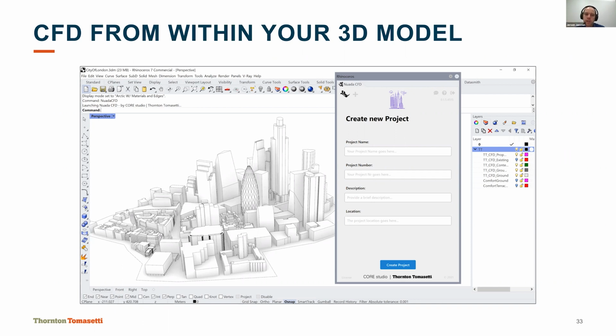What I like about SimScale is they have a specific solver for urban domains, that is Boltzmann solver, which, without going too much into detail, technically doesn't mesh the geometry, and therefore it's actually very gentle with geometry. So you can throw in quite a lot of dirty geometry, which means you save a lot of time in cleaning up the geometry. If you're working with an OpenFOAM big model like this, you could easily spend 2-3 days to actually remodel everything. And with SimScale, I've been seeing that drop to almost an hour. The simulation costs some money, so it is a subscription. It runs fully in the cloud, so by default, that runs in the browser.